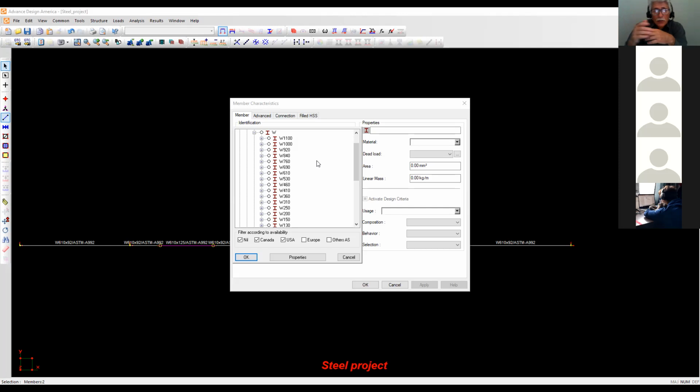So right now I'm gonna pick one. I'm gonna put one in. So the thing we did on XL, what was that? That's only for the girder. That's for the girder with the left cantilever and the girder for the double cantilever. That's all you did. You had to go in and size the drop-in beam, which is the easiest one. It's just like all the beam problems that we've done in class. You've got your MF value, you have your LU value, go pick a beam. What more can I ask you to do? You understand?